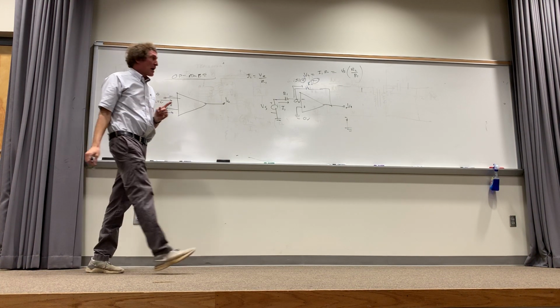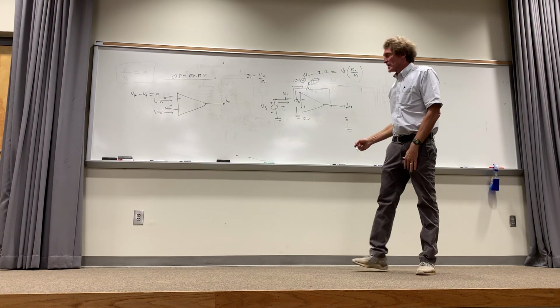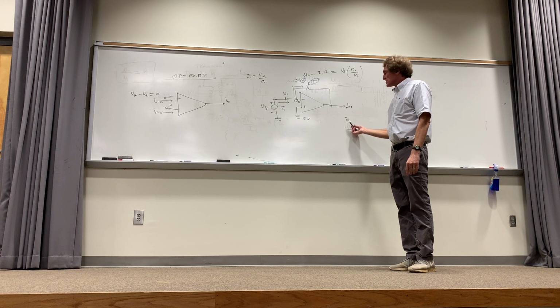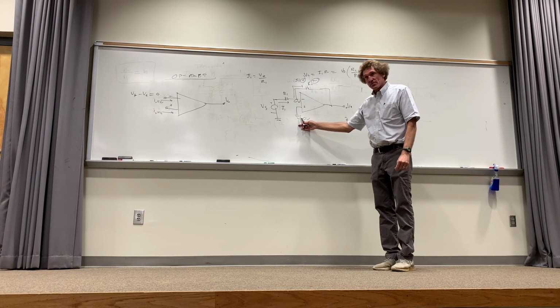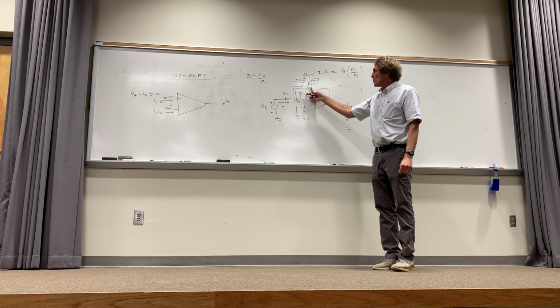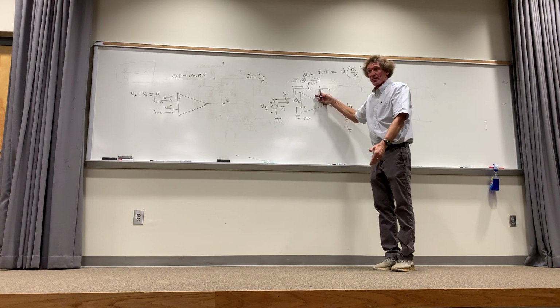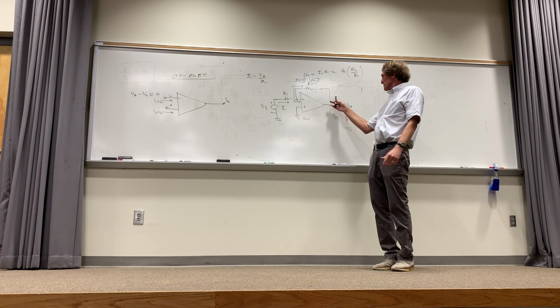Okay. Now, what is the voltage here? This is where people mess up. So watch. If I want the voltage here, y'all see I can start at this negative terminal, right? I always say start at the negative terminal of the voltage you want, and work around. I've got 0 volts here, 0 volts here, agree? But this is a voltage drop, right? It's minus that voltage before I get to the plus terminal there.